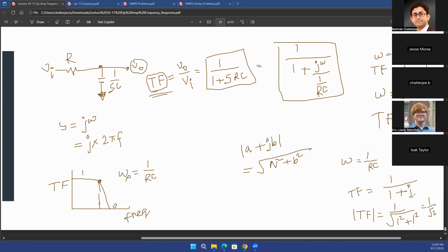So your voltage or current gets squared. Along with that, you have a resistance quantity, but assuming that the resistance quantity is equal at the input and output, you can say that the power ratio between your output and input is the square of the voltage ratio between your output and input, right? So if that is true, what is the power transfer function? That would be the square of 1 over root 2, right? The power transfer function is going to be half.